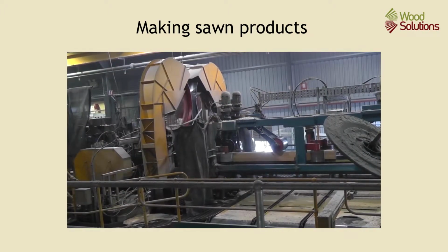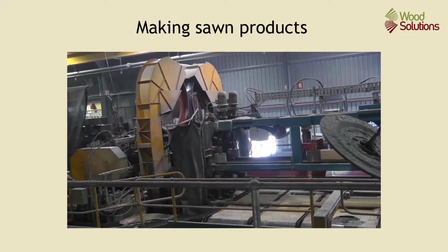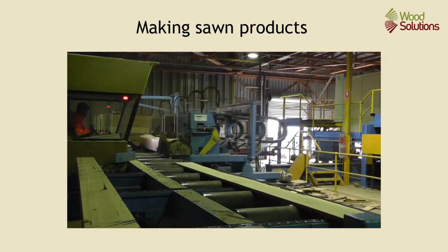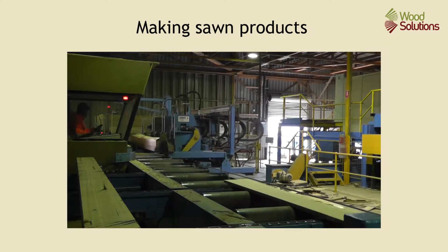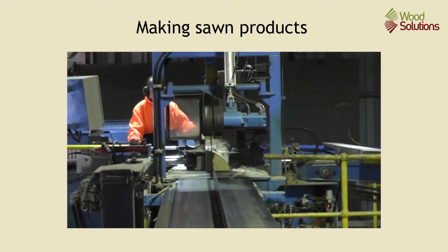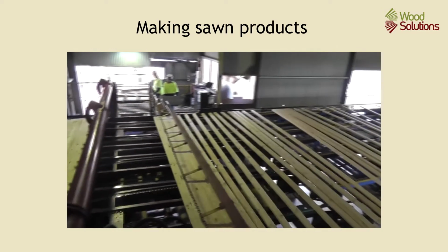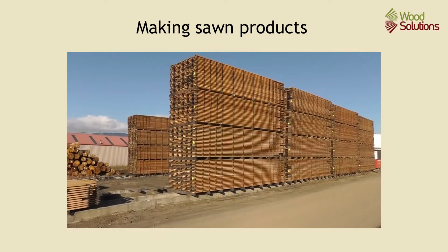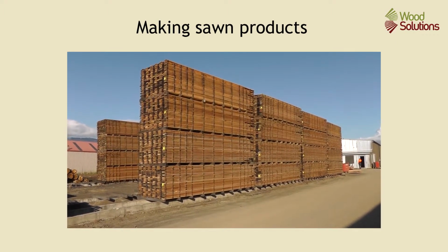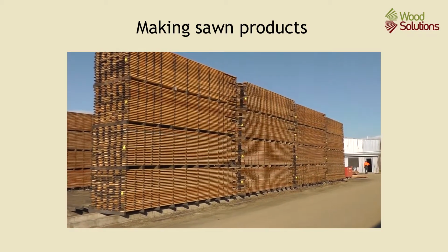The equipment used to mill the logs into boards can range from very high-speed bandsaws to large circular saws with the logs on a carriage, to a single operator bench focused on maximising recovery. Once cut, similar sizes and types of boards are arranged in racks. They are then dried in the air and in timber drying kilns. This is to bring the wood's moisture content down to a level suitable for its final intended application.